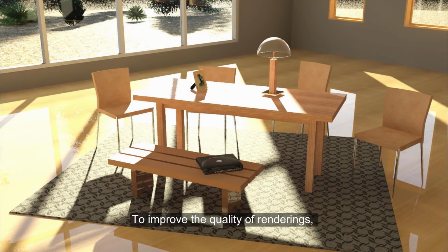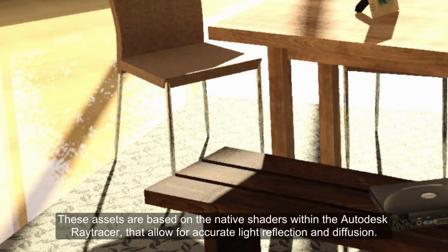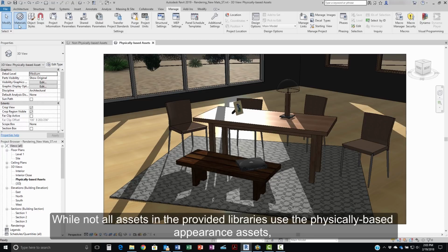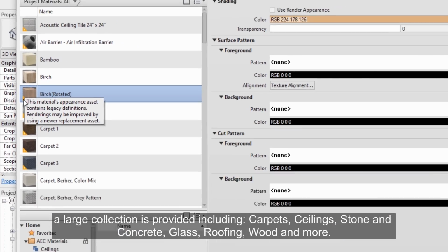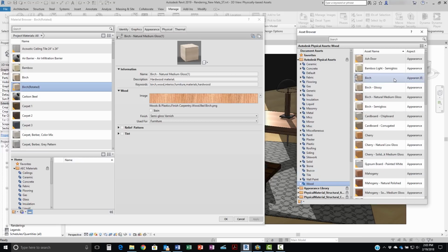To improve the quality of renderings, a collection of high-quality physically based appearance assets is available that takes advantage of the physically based rendering engine in Revit. These assets are based on the native shaders within the Autodesk Ray Tracer that allow for accurate light reflection and diffusion. While not all assets in the provided libraries use the physically based appearance assets, a large collection is provided that includes items like carpets, ceilings, stone and concrete, glass and roofing, wood, and many more.